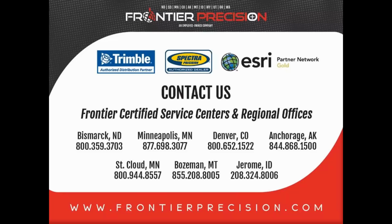So what we see a lot of times, you put a robot on a Dutch Hill tripod, you turn it on, and you'll get a tilt error or something like that, and it'll look like your robot's broken and it's not working right. You call in and you talk to me, the first thing I'll tell you is put it on a different tripod, and 9 times out of 10 it works. So tripods are key. A good wood fiberglass tripod or a Trimax would be my recommendations.